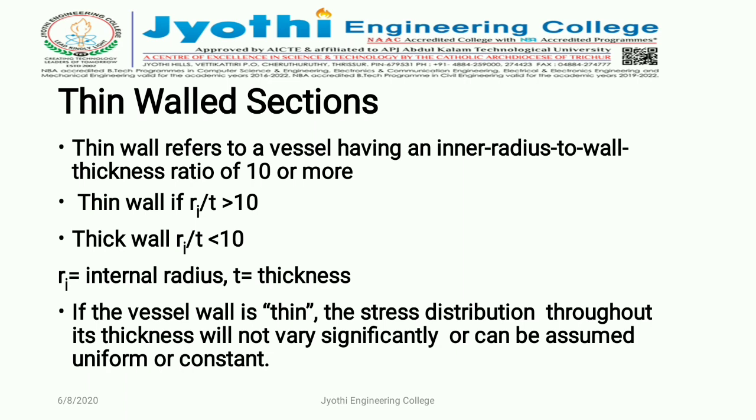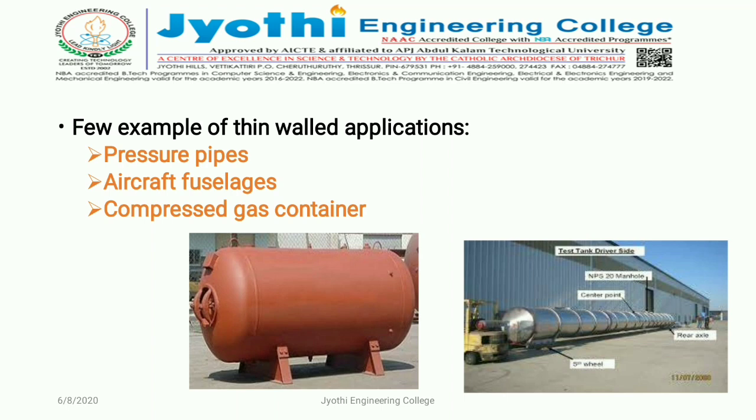But for a thick-walled section, the stress distribution along the wall is not constant. It varies throughout the wall thickness. Now, the main applications of thin-walled sections are pressure pipes, aircraft fuselages, and compressed gas containers.